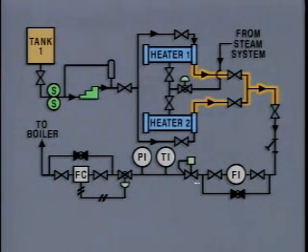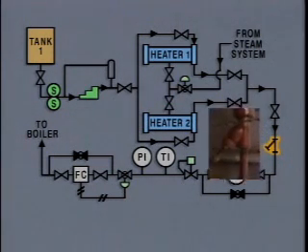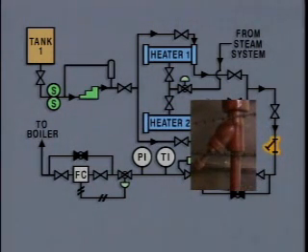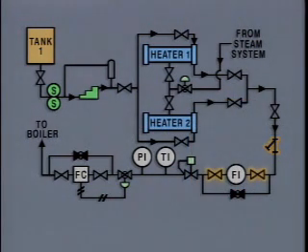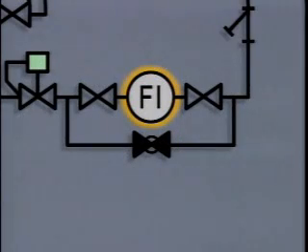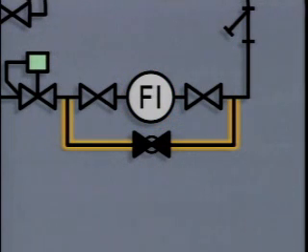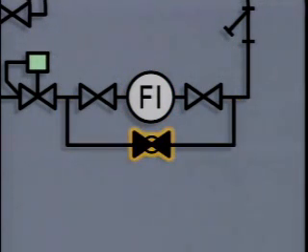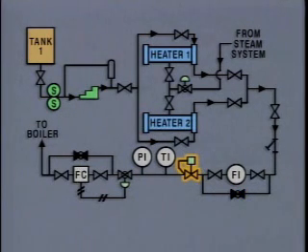boiler. In the line to the boiler, there's an isolation valve and a Y strainer. The strainer traps solid particles that could damage valves and other devices downstream. Next in the line are 2 isolation valves and a bypass line around a local flow indicator. This arrangement allows flow to bypass the flow indicator if necessary. The symbol for the valve in the bypass line is filled in to indicate that it is normally closed during system operation. Next is a pressure regulator, which is represented on the diagram by a symbol for a self-regulating valve.